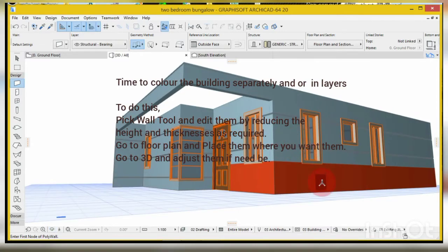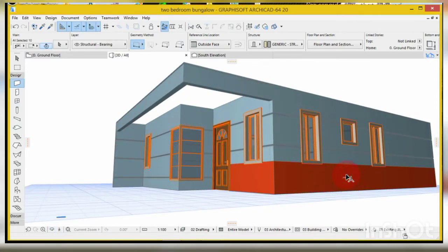You can see it. I can choose this part, as I want to stretch only this place to here. So I have to look unique here. But as I selected it, the thing is grouped because I chose a grouped wall. So I have to ungroup it. How do I ungroup? As it is selected, you come to that standard bar. You can see ungroup, suspend group, alt G. So it has been suspended.